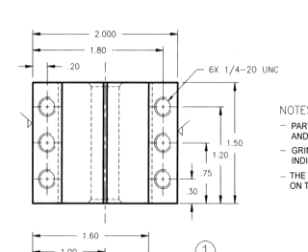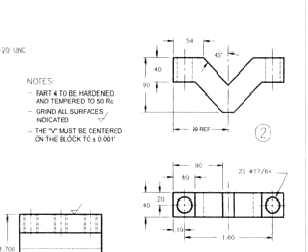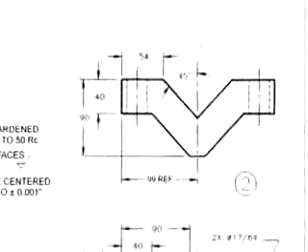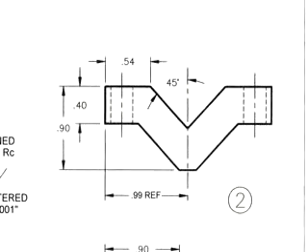The clamp on this project is quite small, but it does have a complex shape that requires a lot of dimensions. We can just imagine how cluttered it would be if we didn't use extension lines. As previously mentioned, extension lines are fine lines that don't attract attention, and they come close to but don't touch the contour lines. This helps to clarify the boundaries so that you don't confuse an extension line with a contour line.